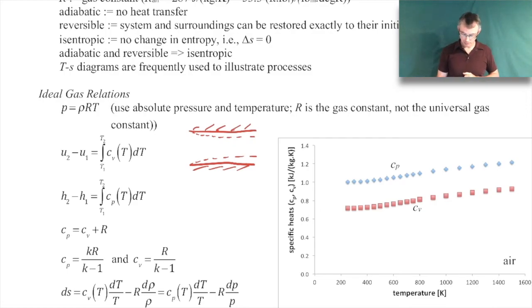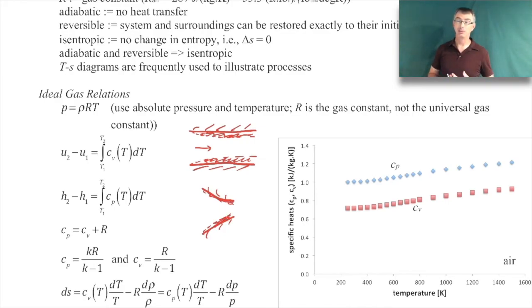And there are, of course, viscous effects in that boundary layer. That's where all the viscous effects are concentrated. But in the core, the flow remains inviscid. So if we have short lengths of pipe, they have to be relatively short, or like a nozzle kind of shape like this, where we get the development of the boundary layer as it goes through there. The boundary layers are pretty thin, so most of the flow field is actually inviscid, right? So it's mostly inviscid, and because if we're dealing with short lengths, often there's not a whole lot of heat transfer that's occurring to the environment or to the surroundings, right?